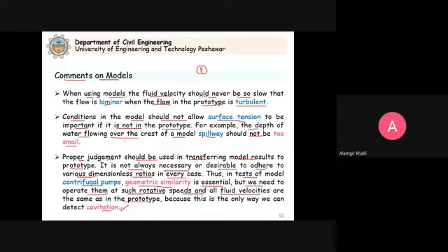Let me explain from this example what I'm saying. Let's say you want to pump water from a lower level. The pressure will be minimum on this side, which is why this is the suction side, the suction pipe. So we have low pressure on this side.